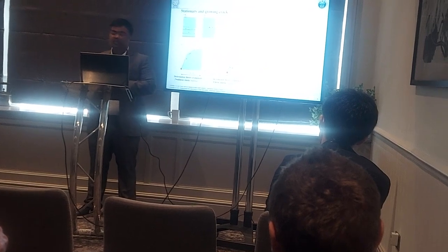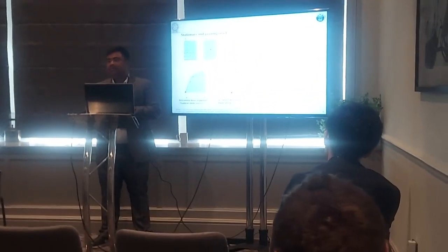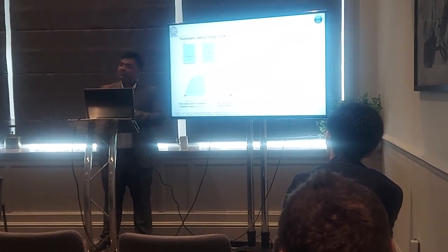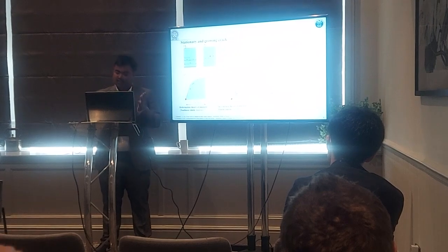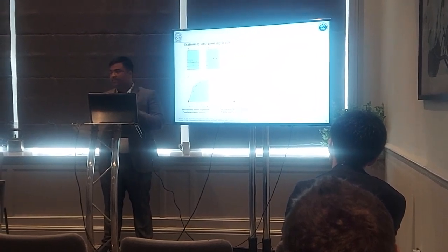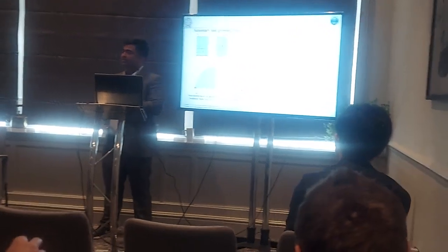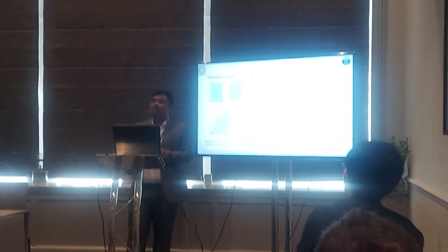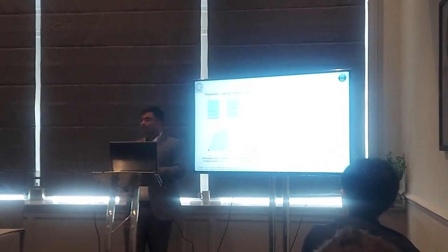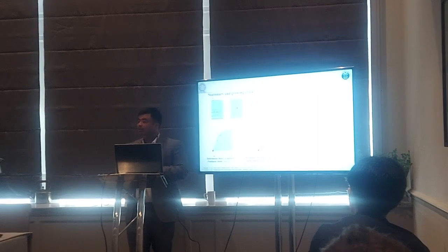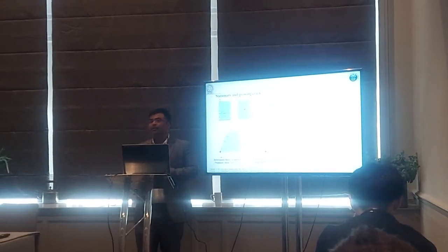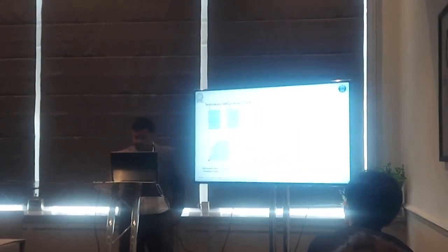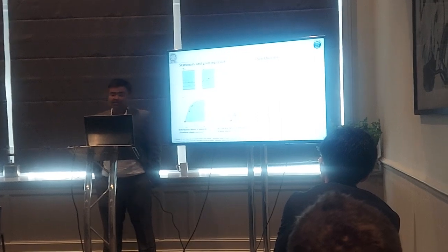But in the case of incremental theory of plasticity, it does not follow the same path. In the deformation theory of plasticity, one stress has one strain value. But with incremental theory of plasticity, for one stress there are two strain values. So incremental theory of plasticity is the real physical condition, with the help of which we can validate the real scenario going on when the crack is growing. For this concept, these are the open questions to you all.